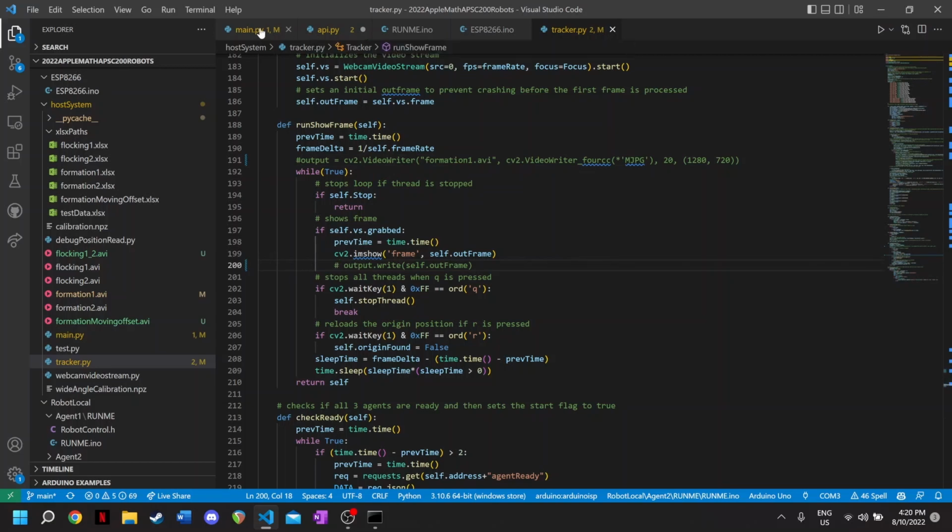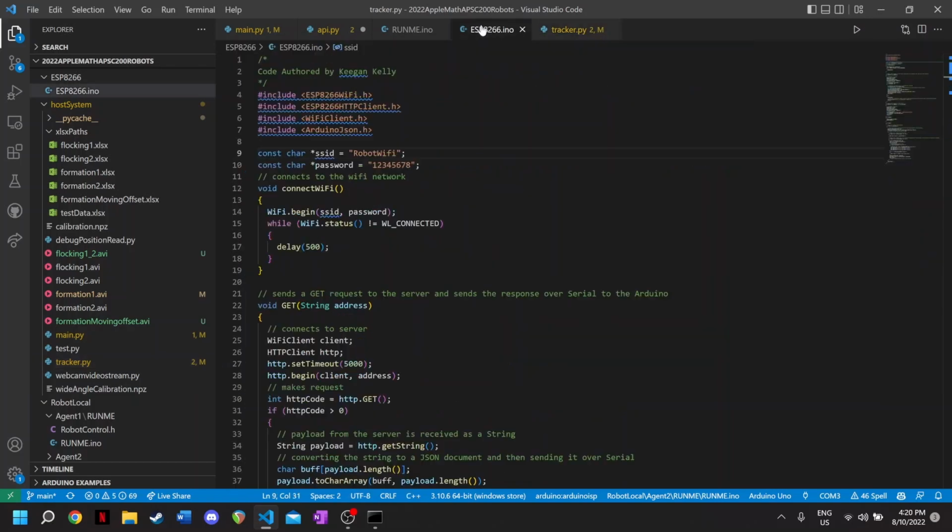So now that we have our address pasted in that couple spots, the next step here, we have to go to our ESPs, which are the Wi-Fi modules on the robots. Make sure you have the correct SSID and password on them. I'm just using the router that you're going to have. Unless you change the network settings, this should be fine, but if you do change the password or the SSID, make sure you change it for each robot.